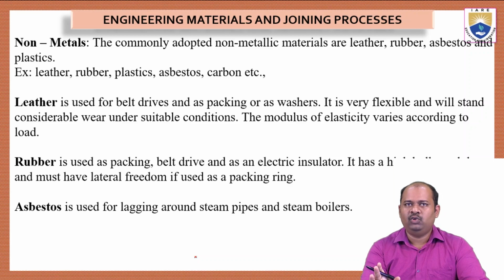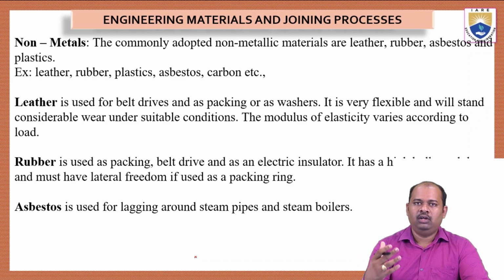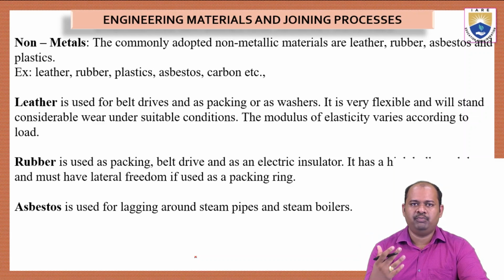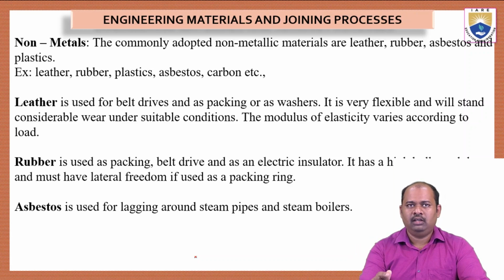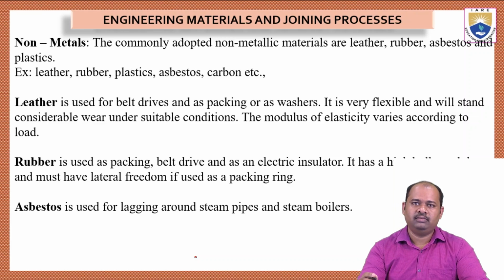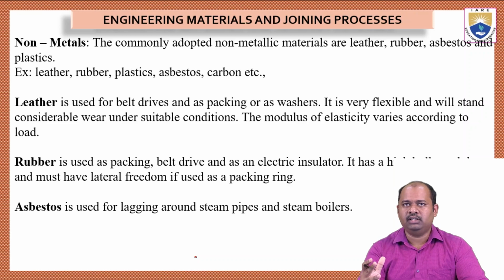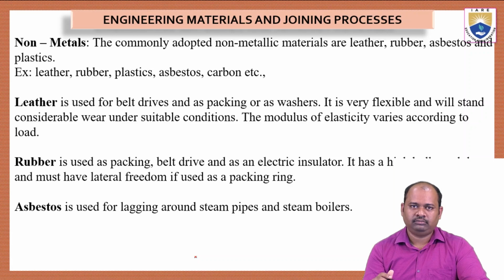These are simply non-metals, yet they have some more applications, like they can be used for insulation, or they can be used for holding purposes, or they can be used to manufacture belts. We can use leather for preparing belts, which can be used for running the power transmissions, etc. So, the commonly adopted non-metallic materials are leather, rubber, asbestos, and plastics. So, these are some of the non-metals which can be applied in engineering applications.